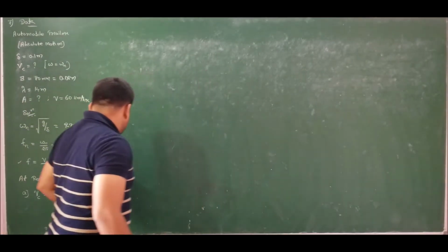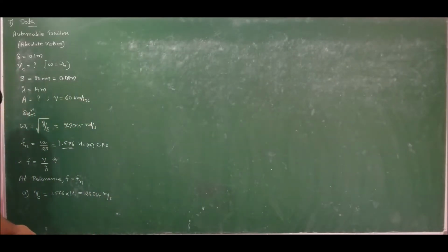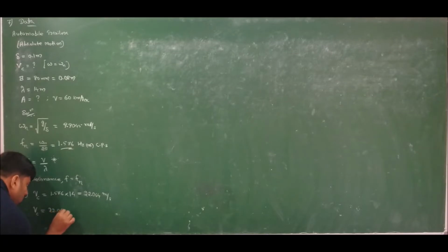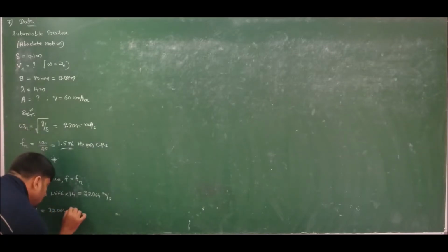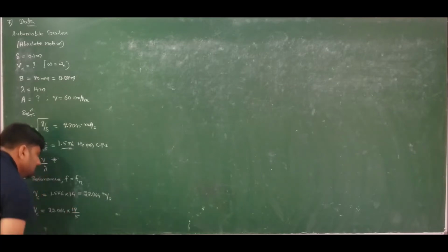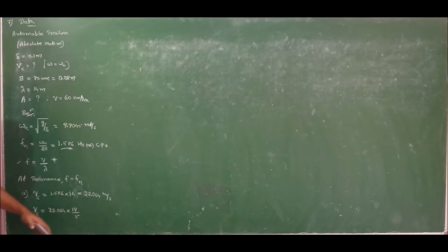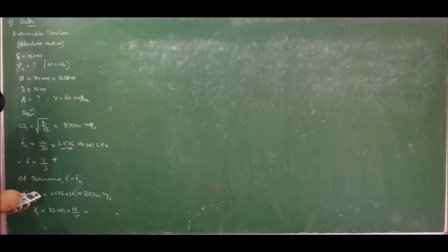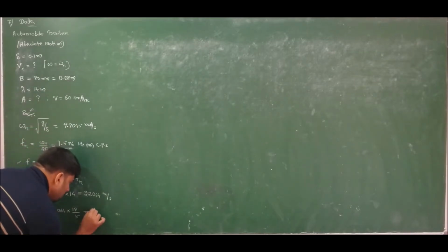So it is a good habit to mention the velocity in kilometer per hour. Hence mention the critical speed in kmph, kilometer per hour. That is 22.064 into 18 by 5, correct? 18 by 5 is the conversion from meter per second to kilometer per hour, which is nothing but 3600 divided by 1000. Into 18 by 5 is how much? 79.43 kilometer per hour.